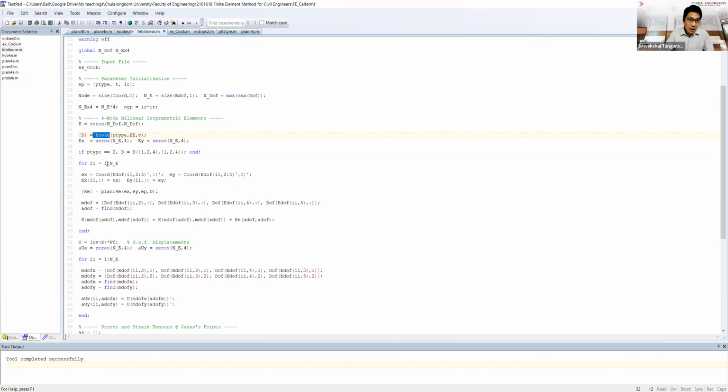And the rest of them, they start to call the loop. The loop here, they try to reassemble. If you recall step number 3, number 4, I say that you have to construct the K for Ki for each member, and you keep reassembling them by using the information on the degree of freedom. So this is how you assemble the K matrix by finding the Ke.